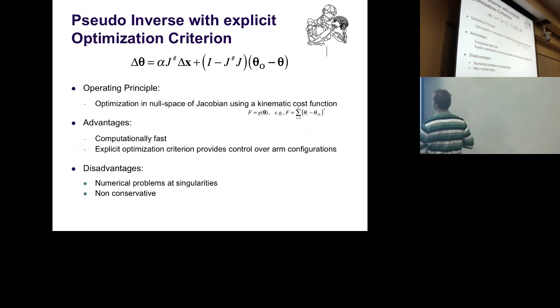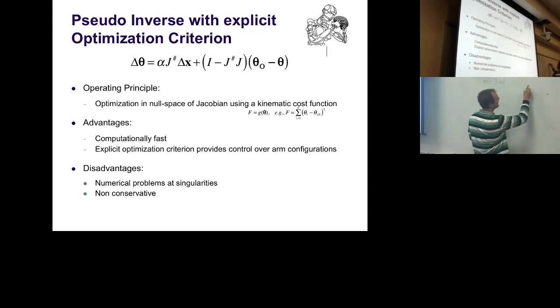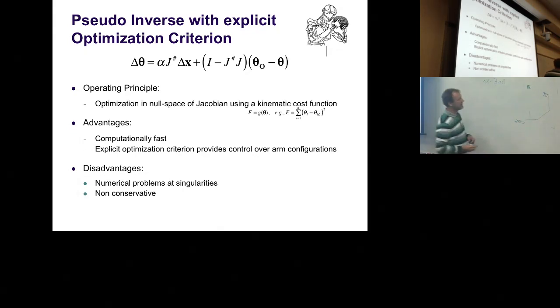Let me verify. Is this thing doing something useful? Differential direct kinematics is, you have the delta notation, delta x equals J times delta theta. Now, I compute currently a delta theta, which is supposed to get me a step on a straight line forward towards my target, which is basically this delta x. Again, I'm currently here. Here's my target. And I compute a tiny little delta x to get forward. And there's some robot arm attached to it. All right.